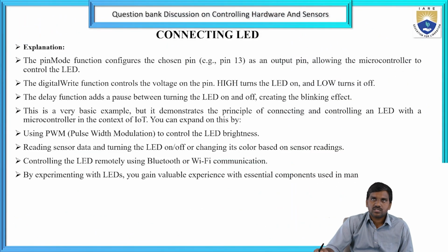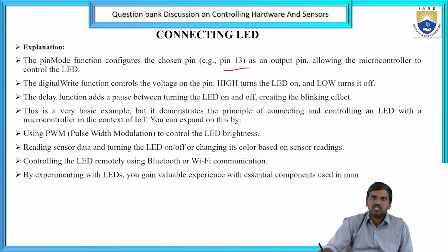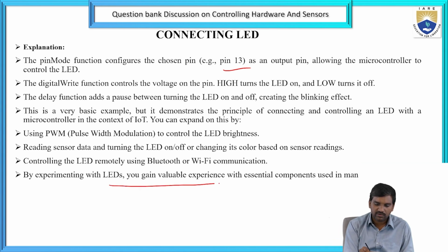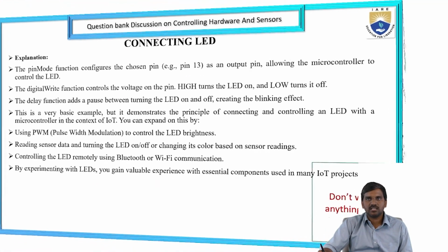The pinMode function configuration: choose the pin, for example pin 13, as an output pin, allowing the microcontroller to control the LED. By experimenting with LEDs, you can gain valuable experience with essential components used in many IoT projects. So these are the explanation of connecting an LED on the breadboard.